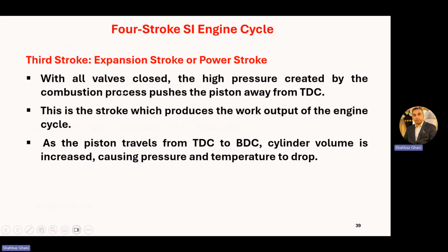Third stroke, the expansion stroke or power stroke. With all valves closed, the high pressure created by the combustion process pushes the piston away from the TDC. This is the stroke which produces the work output of the engine cycle. As the piston travels from TDC to BDC, cylinder volume is increased, causing pressure and temperature to drop.